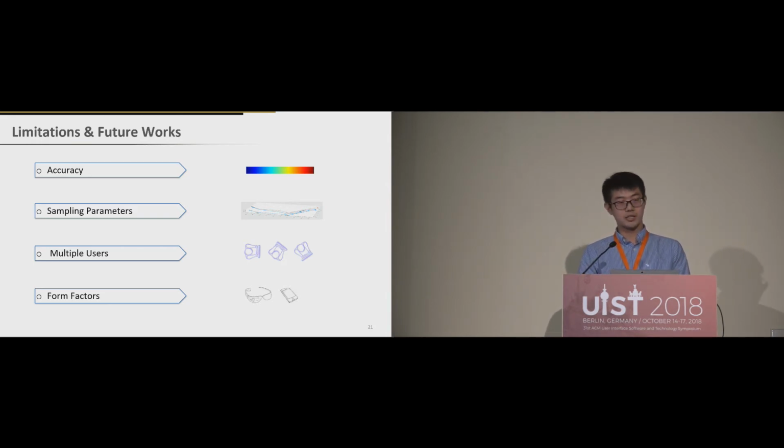First of all, to improve the accuracy, we want to further evaluate the distance measurements quality. For example, we want to get rid of the non-line of sight inaccurate measurements. Although the Google Tango is actually providing a robust SLAM, we still observe some drift. So to fully evaluate our parameters, we want to introduce Vicon system.